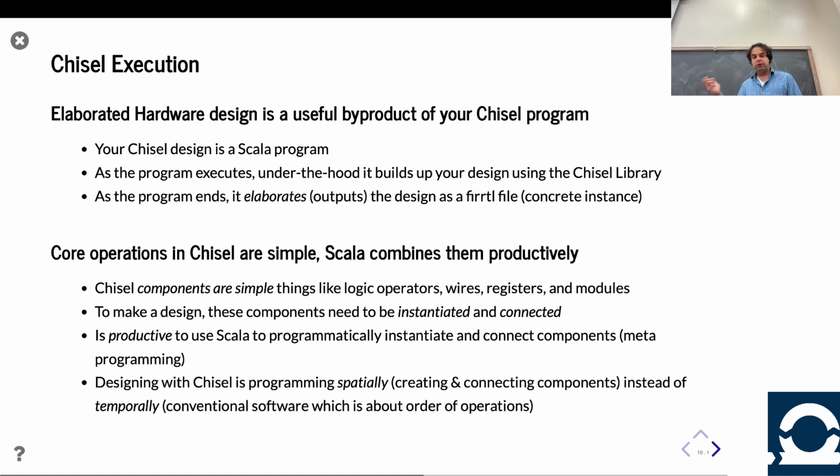Well, the Chisel components are actually all hardware. Like I said, it's a hardware construction language. So things like logic gates, wires, registers, modules, you name it. These are all things you can point to in a schematic. These are all real hardware, right? Everything else in your generator, that's Scala.